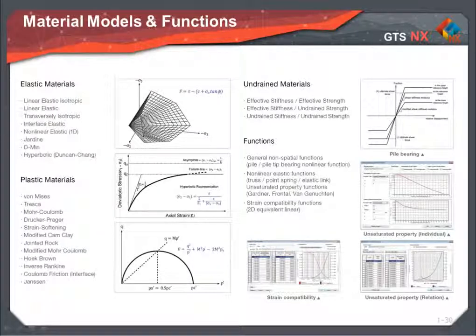There is the linear elastic model having simple behavior, von Mises and Tresca models matching the structural behavior, Mohr-Coulomb matching the general soil, Mohr-Coulomb considering hardening behavior, Hoek-Brown matching the rock behavior, and Modified Cam Clay for the behavior of soft ground. Also, you can directly add your own ground constitutive model by using user-supplied material.